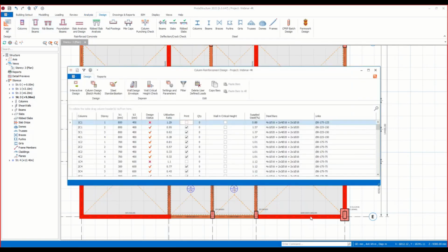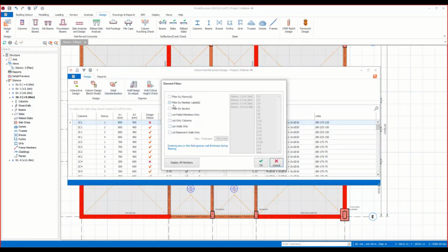By the way, I added the letter R at the end of the shear walls because it will allow me to filter the members quickly. Otherwise, it may be hard to recognize these retrofitting shear walls.